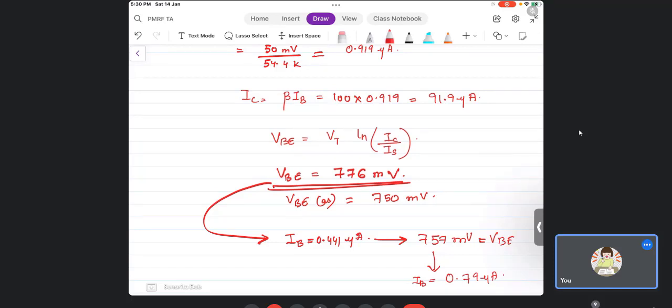So for the resistor divider network, you have to make the base current negligible. The problem is that even if you make the base current negligible with respect to the main current, if your resistor values change a bit, then the negligibility may go away, right?